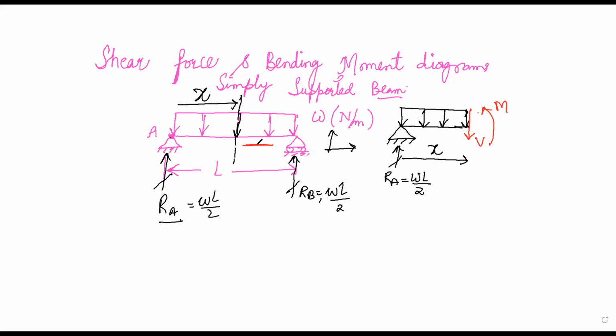Okay, so if you have a shear force V here, then this other end will have the shear force V like this, such that the resultant shear force at this end is equal to 0. In the same way, at any section there will be a bending moment which will be balanced by another portion of the beam, such that the resultant bending moment at any point of the beam will be equal to 0.